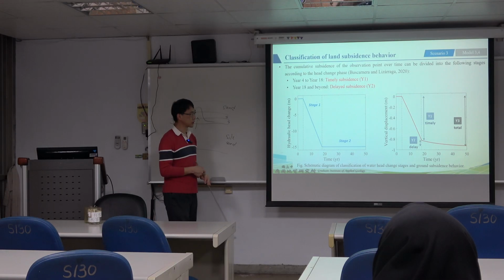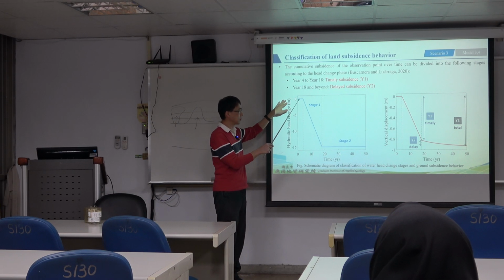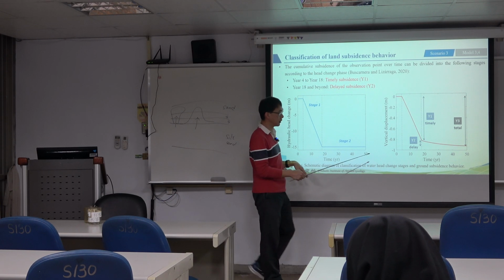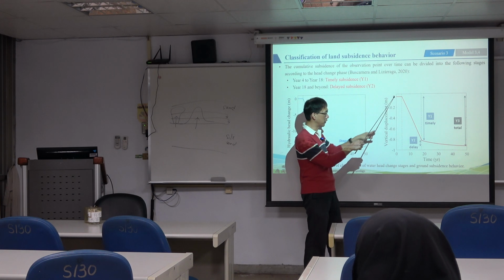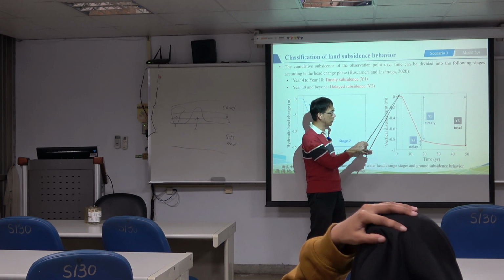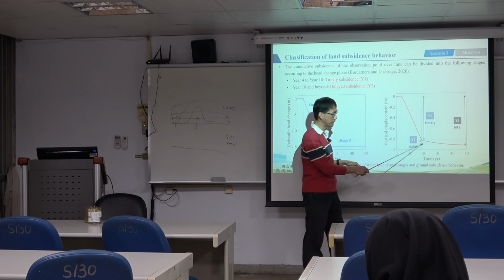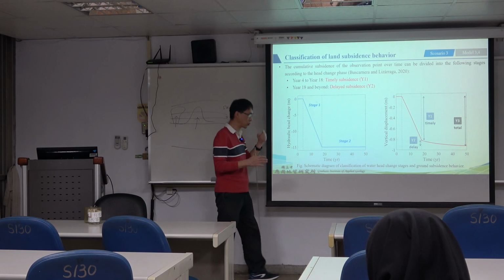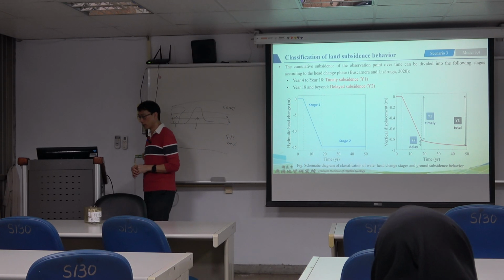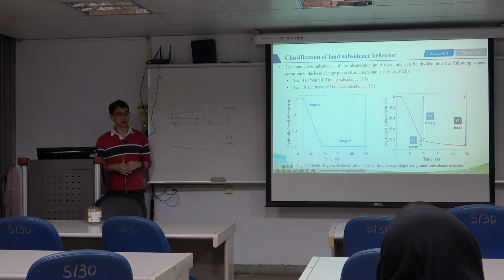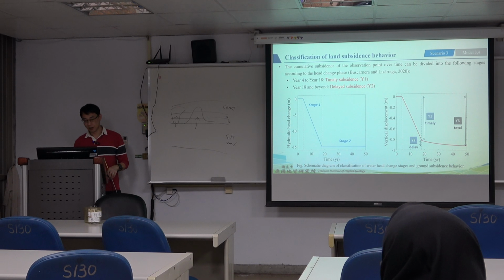In this stage, the hydraulic head change is a very abrupt step change, but your volume change or vertical displacement will change gradually, okay? They have a lag behavior, and the lag is due to the geologic processes. As we know, the hydraulic conductivity K is very small, so the geology takes much more time.